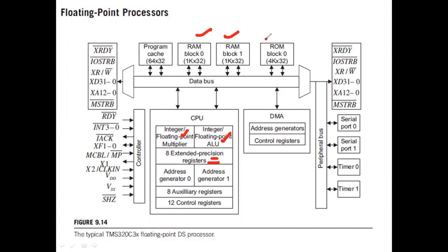Then a ROM. Usually ROM is supposed to hold those constants. What sort of constants? So you design a 13th order filter or a 65 order filter. Coefficients do not change during the program, right? So they are supposed to be there in ROM. Whereas your input data x[n] and whatever I stream on the output y[n], they keep changing. They usually go into RAM.